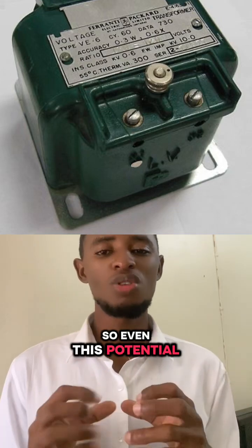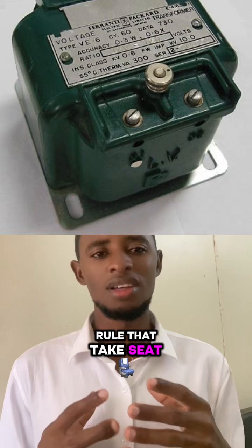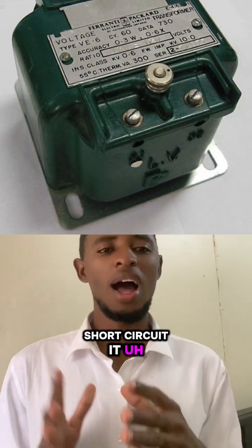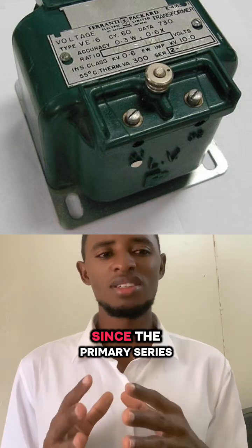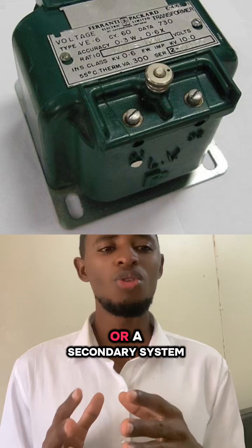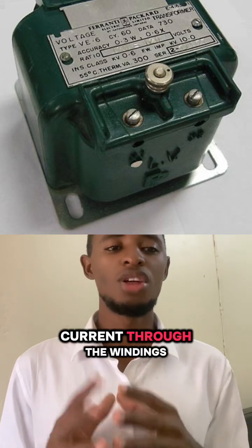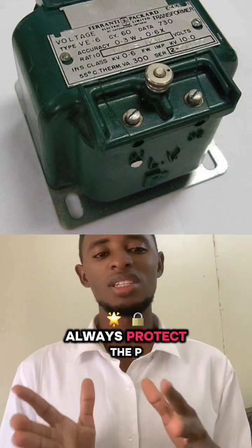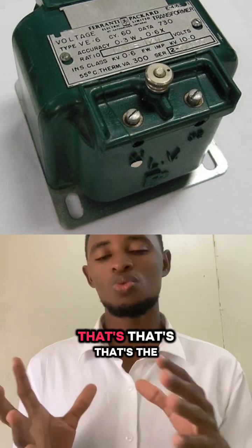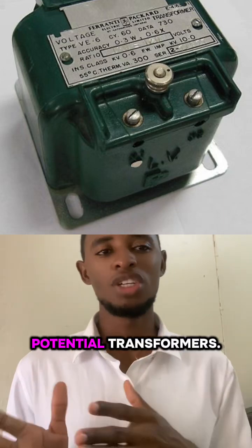Even this potential transformer has a golden rule. That golden rule states: never short circuit a potential transformer secondary, since the primary sits directly across system voltage, and a secondary short reflects as a very high fault current through the windings. Always protect the PT secondaries with fuses or MCBs. That's the rule that governs the potential transformers.